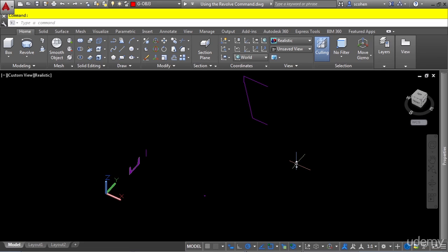You use the Revolve command to create an arcing or circular 3D model from geometry representing a profile of that model. When you revolve a profile, you spin the profile around a defined axis. The amount of revolution can be a full 360 degrees or any start and stop angle within the 360 degrees. You create a solid model if you select a single closed loop object as the profile. If you select open loop geometry or a closed loop composed of separate objects, then you create a surface model.